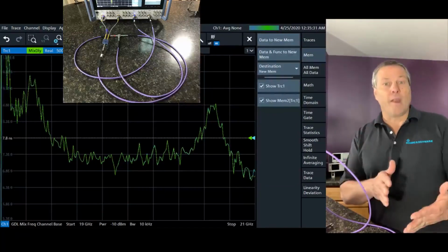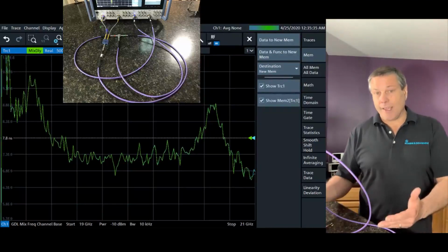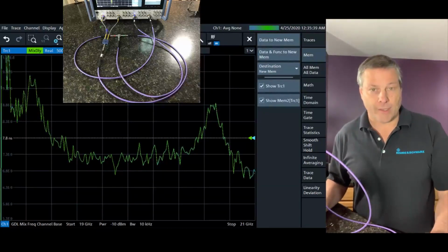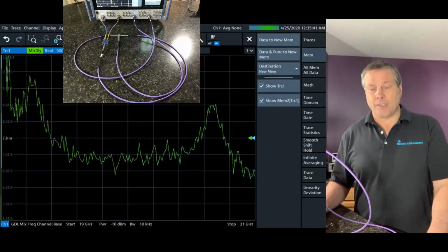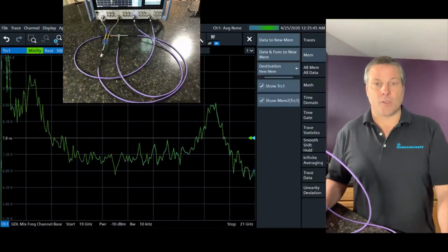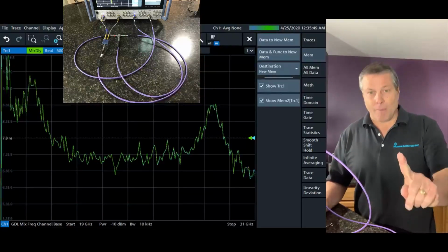and then you wait here. I'm going to reconfigure the test set. I'm going to recalibrate with the reconfigured test set, and I'm going to show you the second trace using technique number two, which is to take the two-tone signal that's combined and run it back into the source in port 1 of the port 1 coupler. Okay, be right back in a moment.